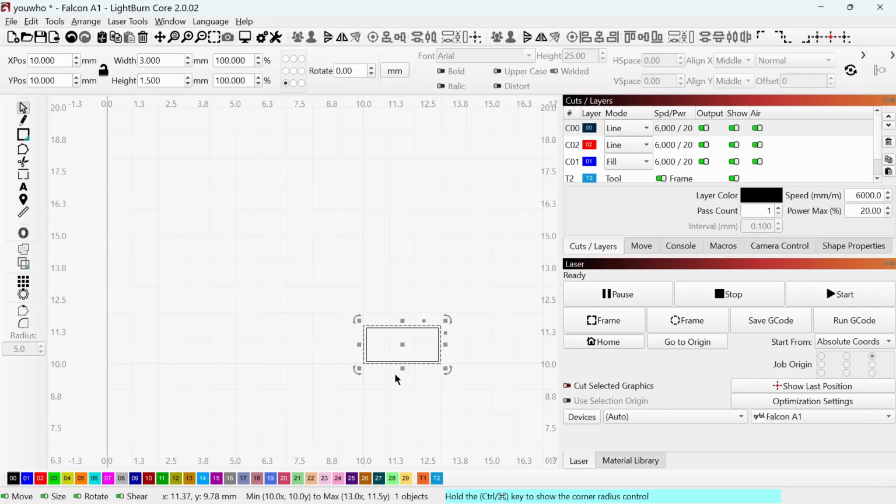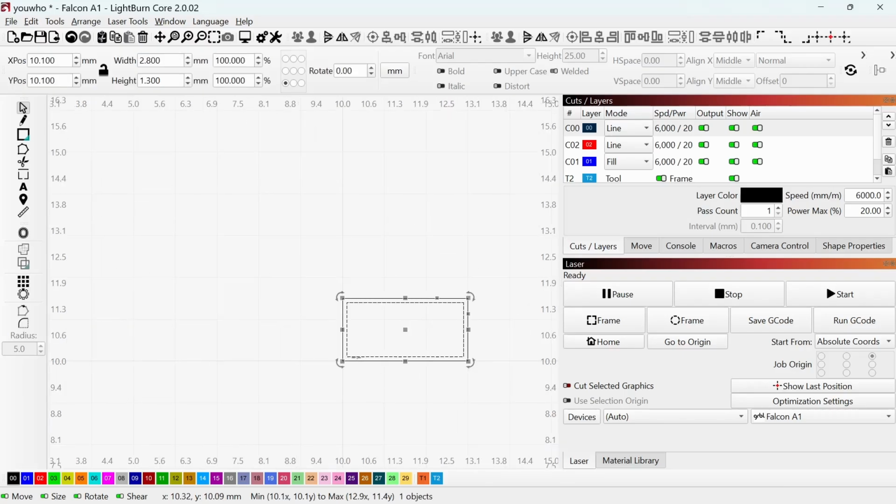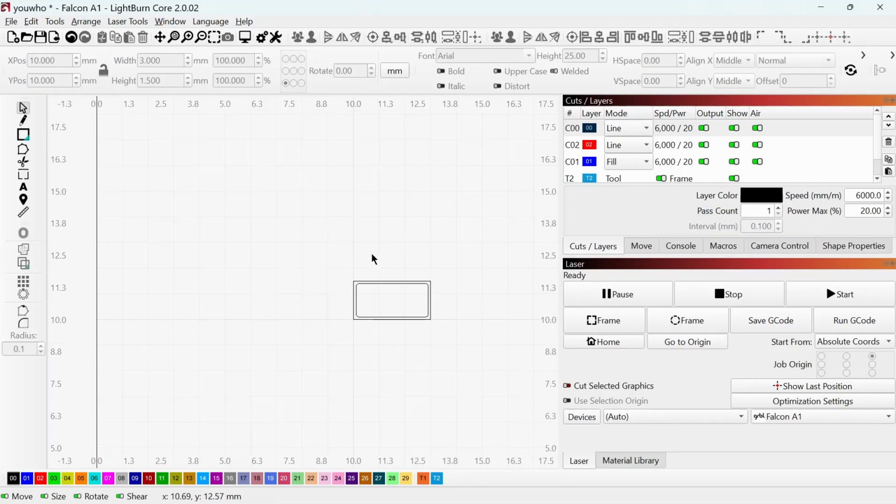Okay, so let's make the brick a little bit fancier as well. So if I select the inside part, come across here to radius. At the moment it's set to 5, I'm going to put it at a radius of 0.1. Come across, on the corners, you'll see the little target, that comes in. So if I go back to the select tool, select the two of them and lock them together by grouping them. Put up here, group. That is them in place here, folks.